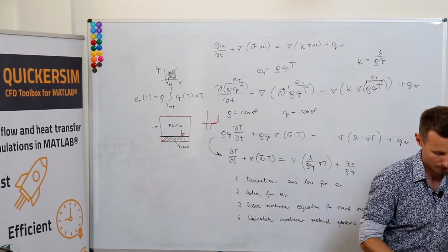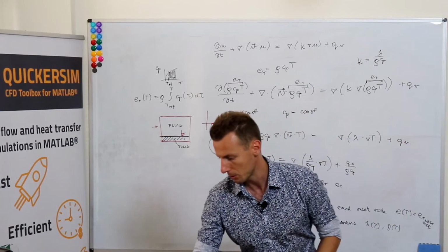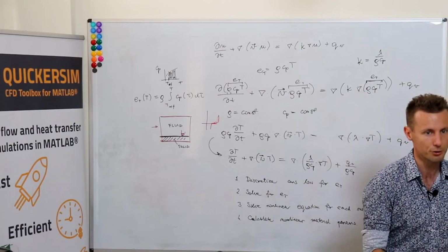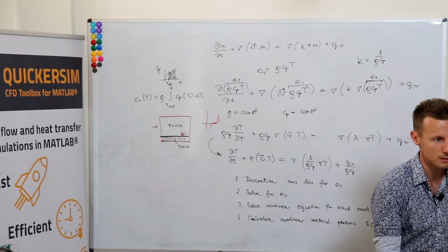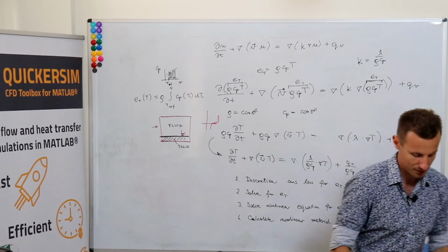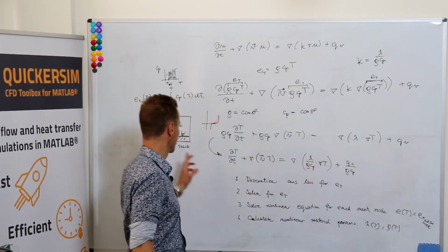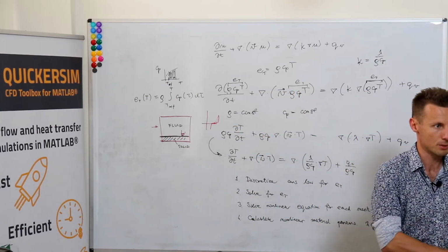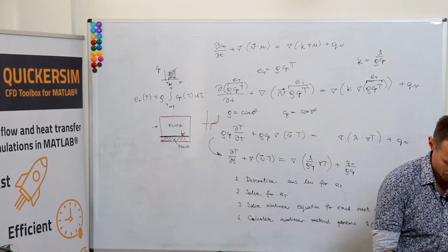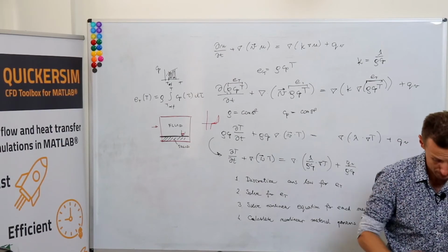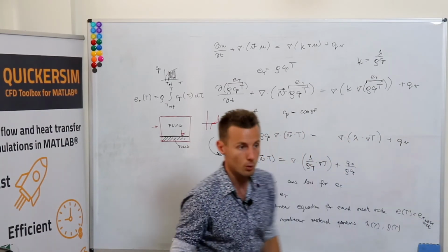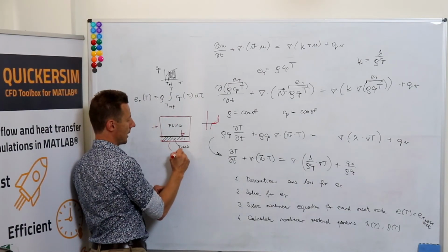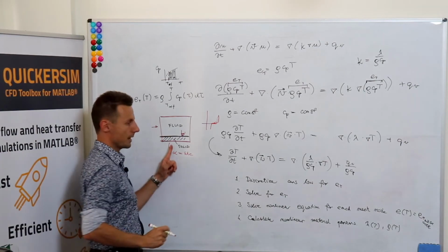And I think many people, especially people who know something about simulations, but they do not work with heat transfer simulations on a daily basis, do not understand that and they would like to input these parameters to the simulation. No, it's not how you do it, and it's basically wrong. What you can do, in turn, is you can define some alpha or heat transfer coefficient here.